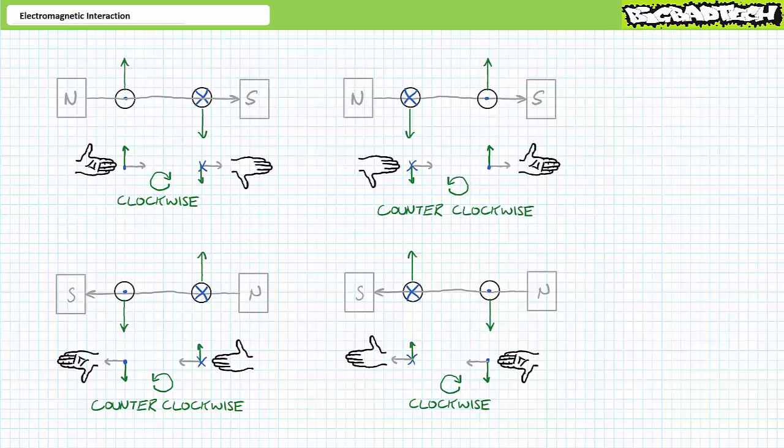The observant among you might be drawing this conclusion. In order to swap the direction of rotation, one can change either the orientation of the magnetic field or the direction of current flow, but not both. We'll examine how this phenomenon is put to use in controlling the direction of DC motors in later lectures.